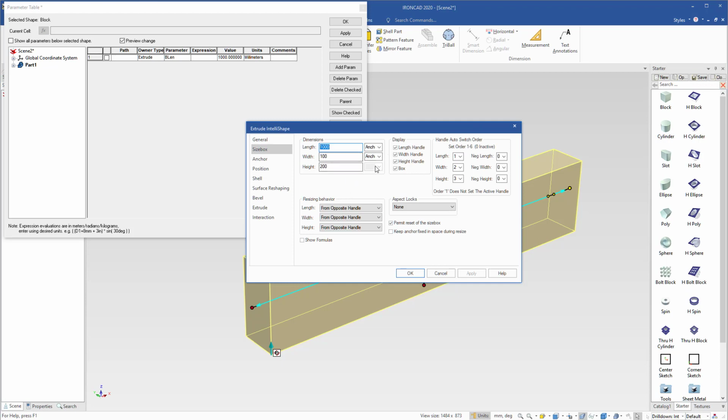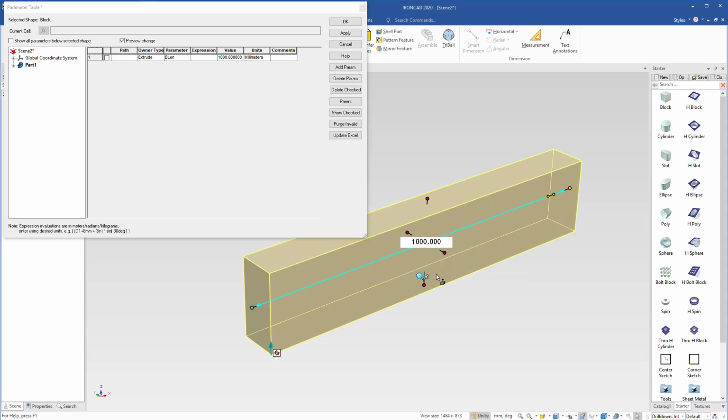Inside of our handles you can actually tie these to formulas, which means parameters. So if we go ahead and select that option, we can set any one of these. In our case it's a length. We're going to set that to the B length value. And we're just going to set it to do either the start or end. You can just choose the end in this case, or start. It depends on your model and how it started, but it's basically based on this arrow location. But we're just going to set it to the end and just leave everything else the default, and that will basically drive that for us.